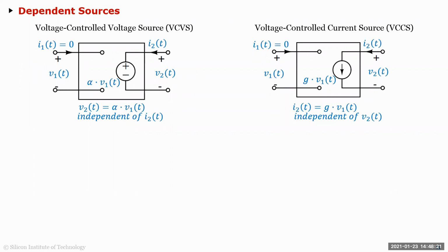And then the voltage controlled current source: the input is a voltage, again with infinite impedance, but the output is some G times the input voltage. This is what's called a transconductance, where you're converting from voltage to current. Basically, this is a model for a transistor. Your input is the gate voltage and the output is a current. In a transistor it's gm times or beta times or whatever it is; here it is G times. So if you're modeling a transistor, this is how you model it.